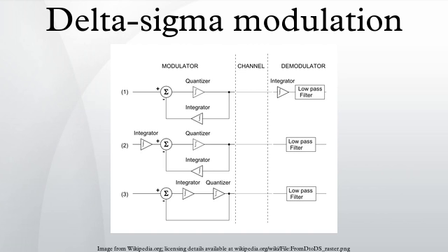the trigger edge so that there is an appreciable delay before the impulse starts. After the start of the impulse there is further delay while the integrator climbs back past the threshold. During this time the comparator output remains high but goes low before the next trigger edge. At that next trigger edge the impulse timer goes low to follow the comparator. Thus the clock determines the duration of the impulse.